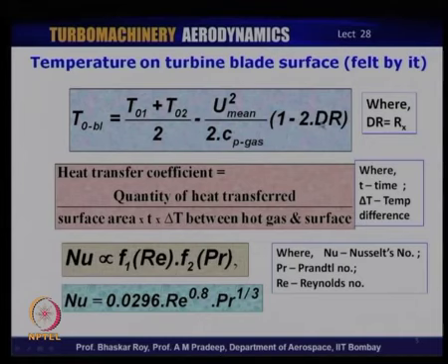Now, this gives rise to the situation that the blade temperature as felt on the blade surface, the average blade temperature, is something quite different from the gas temperature. So, gas temperature is not what the blade feels. The blade feels a different temperature arguably, and as is quite obvious here, it will feel a temperature lower than the gas temperature.